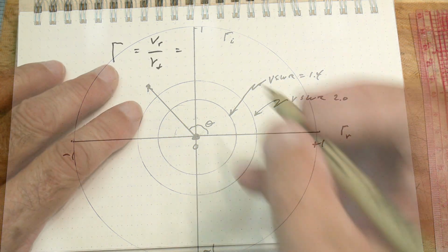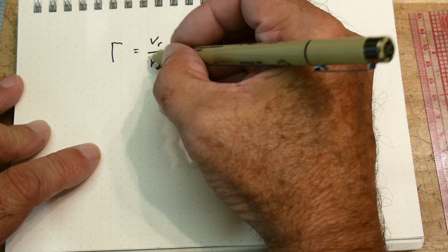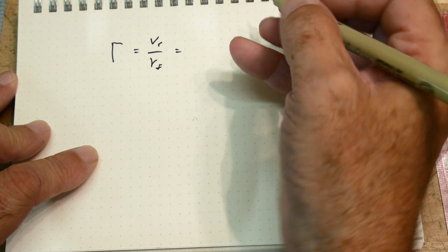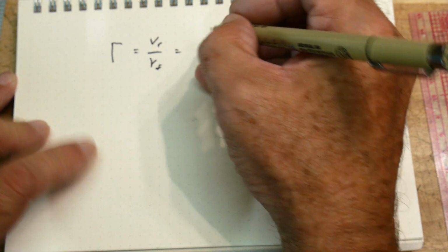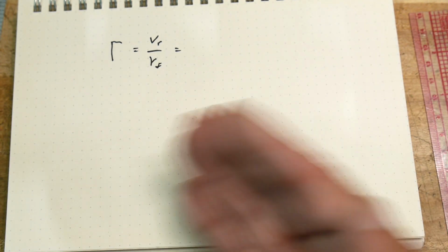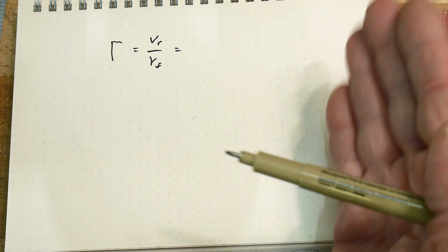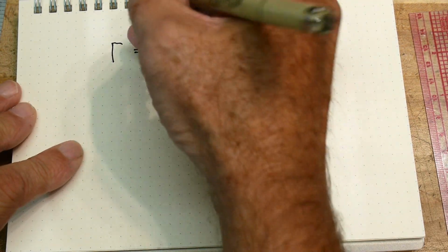All right, we've introduced gamma, which is the reverse voltage divided by the forward voltage. Okay, this is a little f. Well, you can do some math, and you can figure out that what we're really wanting to measure is the impedance match, right? That if you have a perfect impedance match, then gamma goes to 0. So remember impedance.